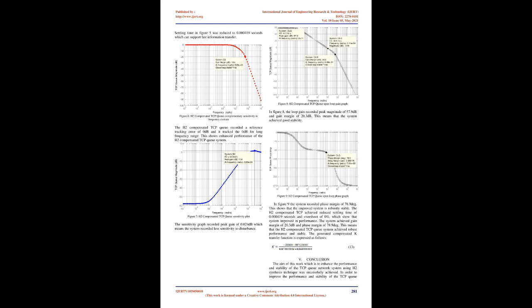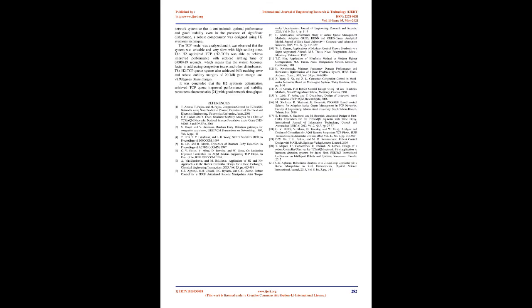Some recent works have shown the benefit of using proportional feedback in TCP/AQM networks. By using proportional feedback, the marking probability is proportional to the instantaneous queue length. They worked on addressing the nonlinearities directly and establishing some stability results when the marking is proportional. In the case of delay-free marking, they showed the system's equilibrium point to be asymptotically stable for all proportional gains.